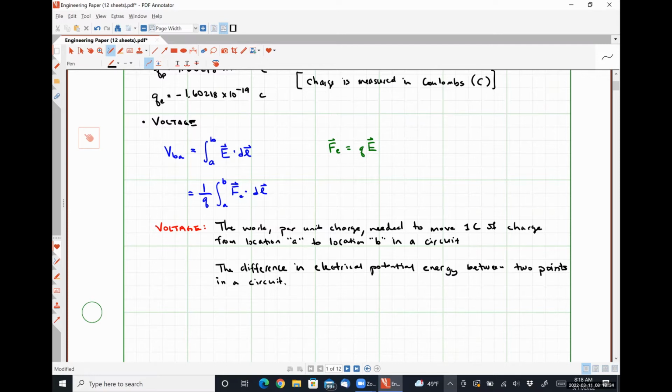Let me ask you a different question. Does the presence of that voltage require that a current be flowing? Absolutely not. If I have a battery and I hold it in my hand, not connected to a circuit, it still exhibits a difference of electric potential of 1.5 volts, despite the fact that there is no current flowing whatsoever, right? So we can observe voltages without current flowing, okay?